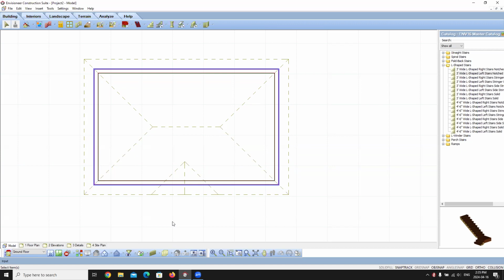I'm just going to go over a quick review of what we've covered in today's class. There are different ways of inserting a roof in Envisioneer, and the method you choose depends on where the roof will sit in relation to the exterior walls. Roofs can be customized to achieve virtually any style or configuration that is desired. You can use the Roofs by Perimeter tool to automatically insert a roof over the perimeter walls on a selected building location. The roof is going to be connected to the walls, so if you change the wall layout, the roofs will also change with it.